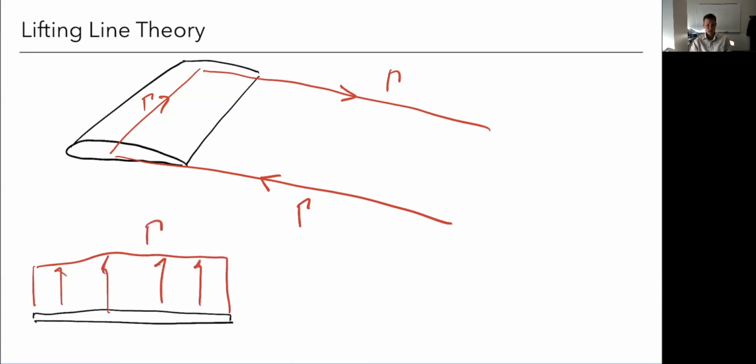Gamma, we know that that is unphysical, not realistic. For one, the lift distribution must go to 0 at the tips, right here at the wing tips. It can't have this infinite slope as we go to 0. There's no surface here at the tip to support a pressure differential, so it's going to have to go to 0 towards the edges here. We also know it just doesn't look like that kind of a shape. Typically, the lift distribution for just a wing, ignoring fuselage or other interactions, might look something more like this, right? At the very least, we need to go to 0 at the tip.